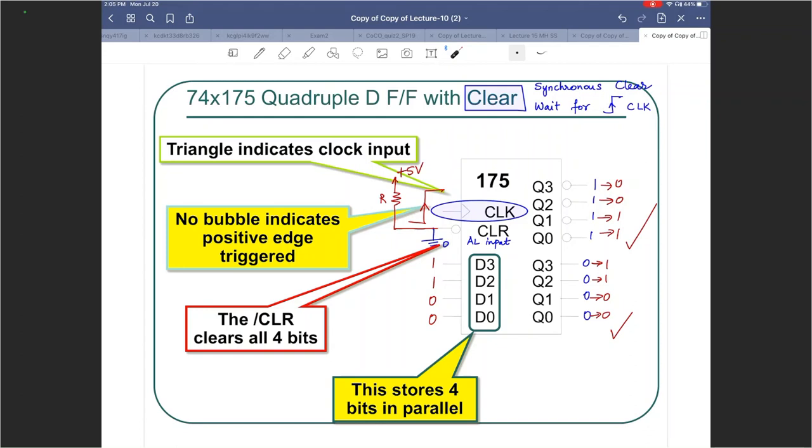After that, you can keep changing the D input and clock things through, and then your Qs will keep changing. So you don't need to clear it every time. Does that help answer your question, Alan?